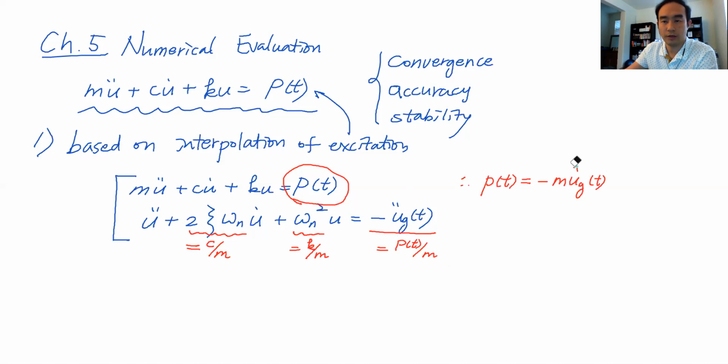One of you asked me about the ground acceleration, the earthquake ground motion record, for El Centro ground motion. The first column was t, 0.001, 0.2, or whatever, depending on delta t. And the second column, usually, is the u double dot g.